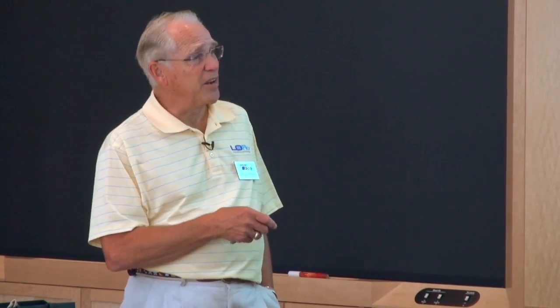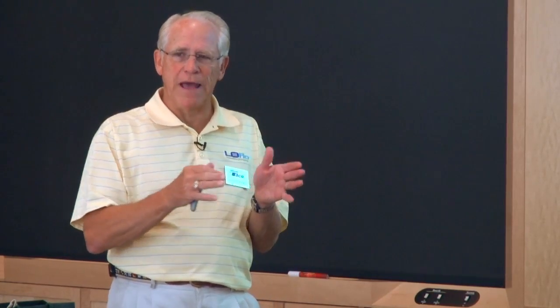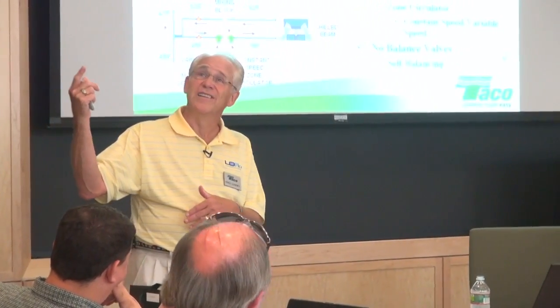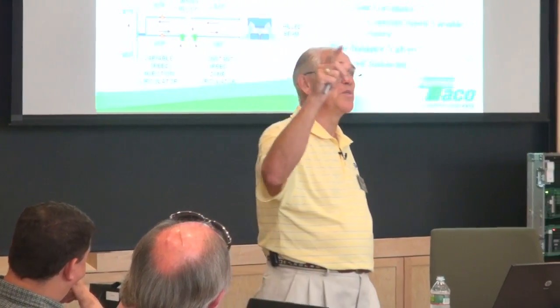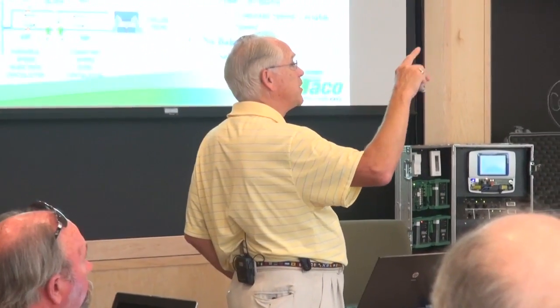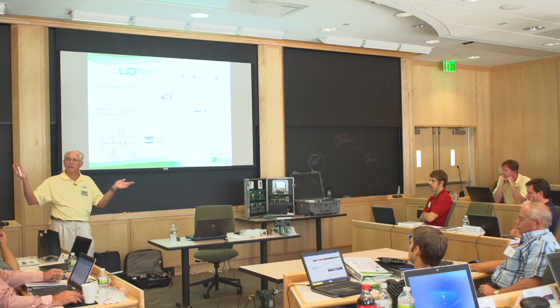What you'll discover in a chill beam system is you're going to have more devices to balance hydronically than you would have. As an example, in this room, if I had a fan coil unit, I'd have 1 balance valve. Instead, we have 1, 2, 3, 4, 5, 6. We got 9 chill beams. So that increases the balancing cost by a factor of 9. That's a big deal. Plus, you also have to balance the airflow.